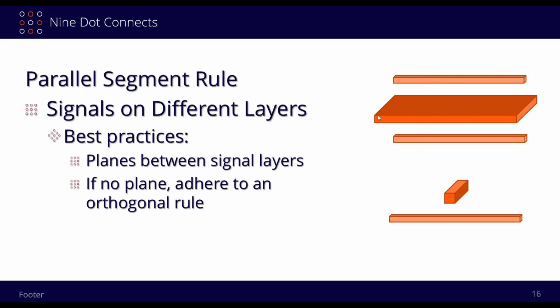And so we should never really even have what we had on the prior slide, two signal layers without some type of reference to a ground plane. And yeah, you can pour a polygon pour on the top in Altium so that you can flood it with copper and reduce some of the noise, but that's no guarantee that you're going to have a clean current loop to return to. If you are working for Dell, I know for a fact, based on the literature I've read, that they don't want to put this extra layer in here. It's to save on cost.